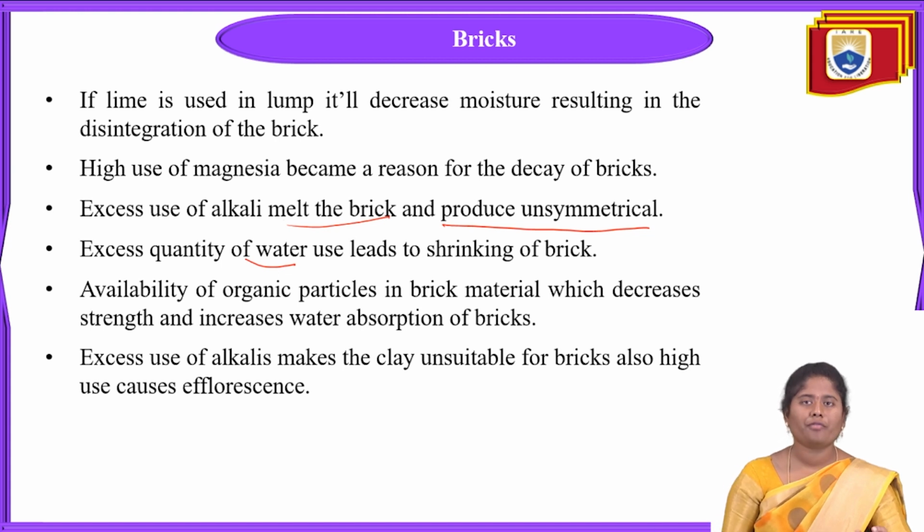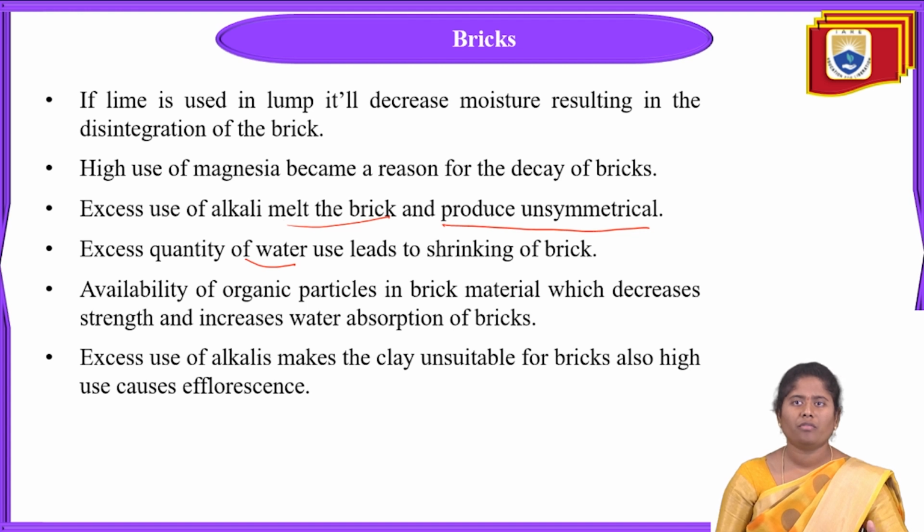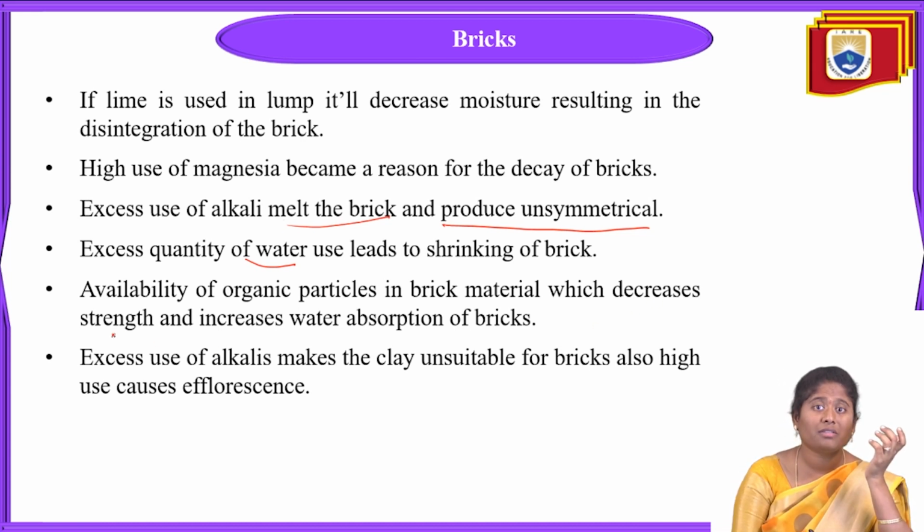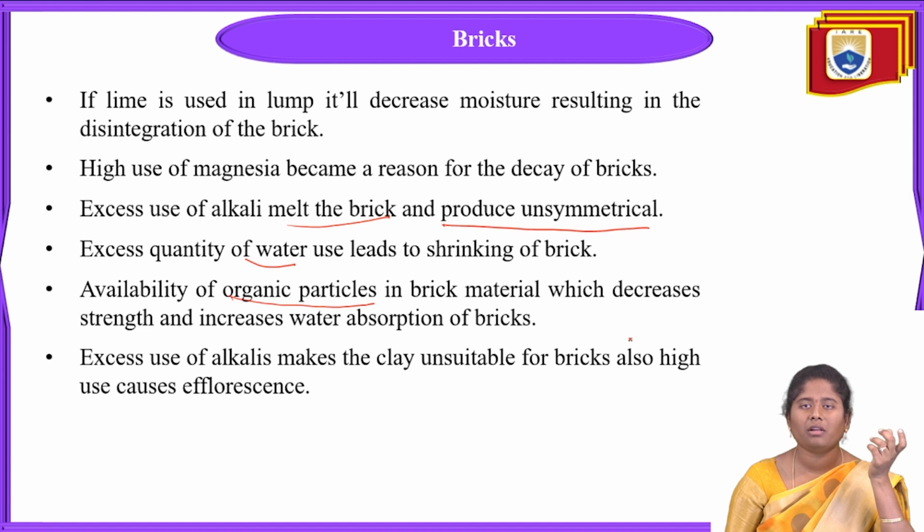Next is organic material. If you add some organic material that is available for the manufacturing of bricks, only some percentage of that organic material should be added. If we add more, it decreases the strength also. Okay, if you add these organic particles, we are manufacturing these bricks using clay only.